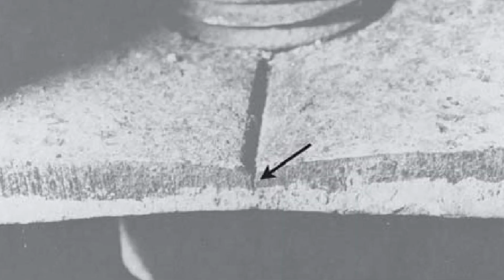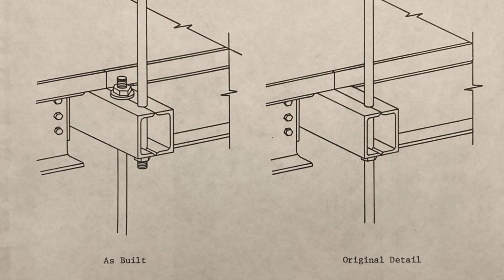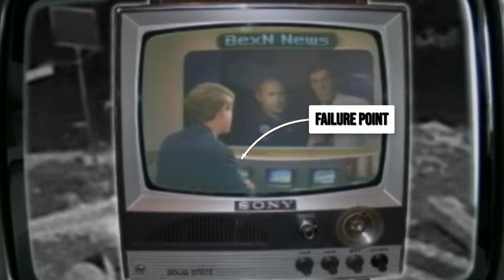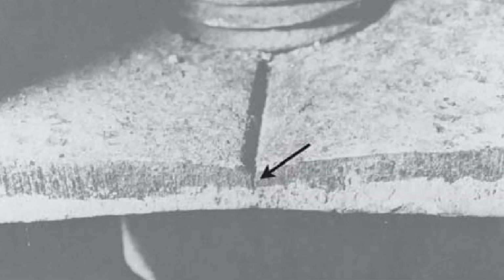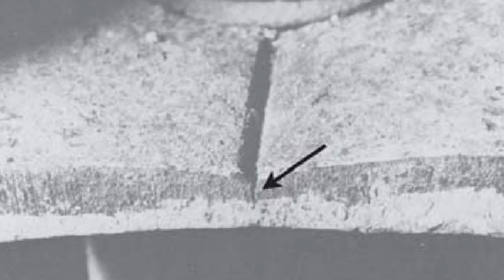Metallurgical inspection of the failed beams from the collapse site showed identical fracture patterns to those produced in the laboratory. The sequence was clear. As the crowd filled the walkway, the stress at the east end of the middle box beam surpassed the steel's limit. The weld cracked, the web split, and the connection unraveled in seconds.